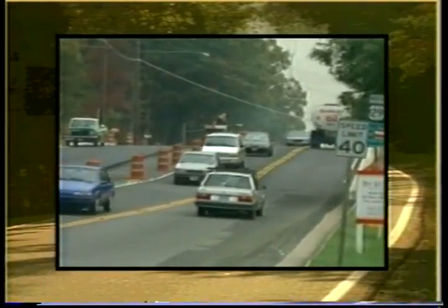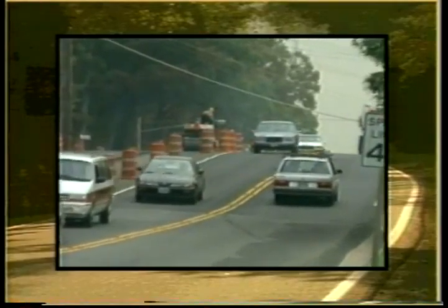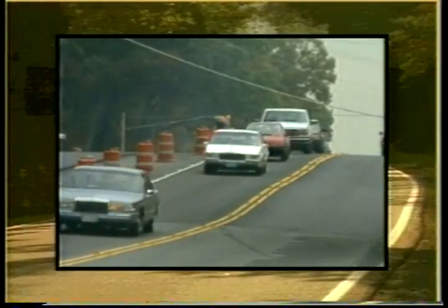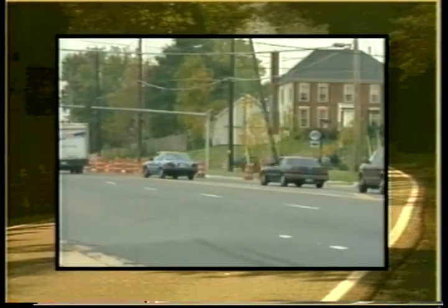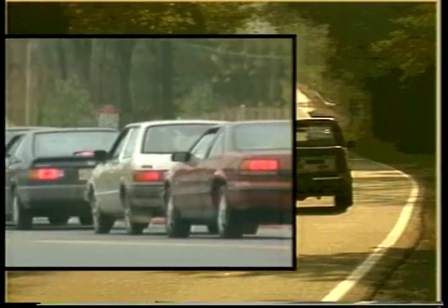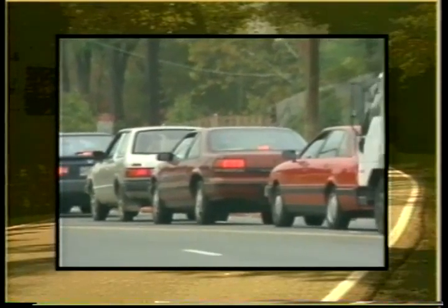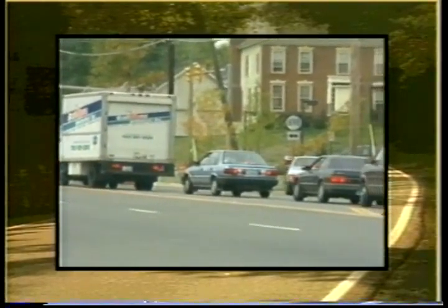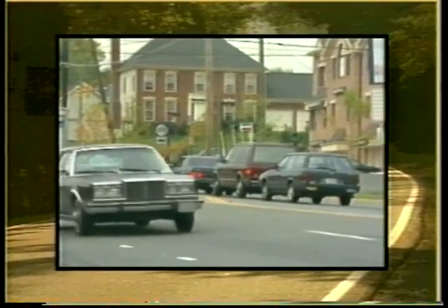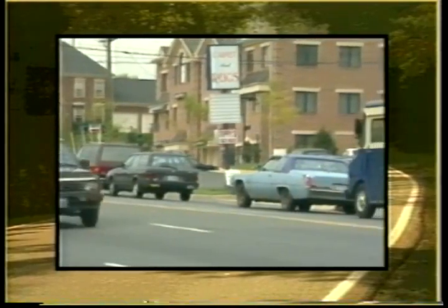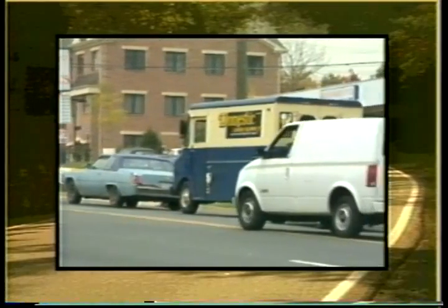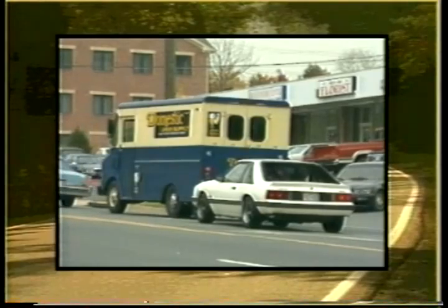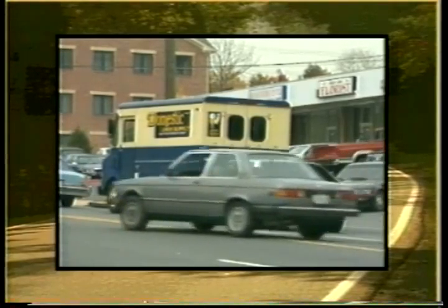Vehicle delay. The estimated travel time through the work zone is compared to the optimum travel time on the same roadway when it is not obstructed. Vehicle stops. Where a reduction in highway capacity occurs due to construction activity, vehicles can come to a complete stop, resulting in considerable traffic backups. Traffic engineers determine the number of stopped vehicles in a given highway segment.